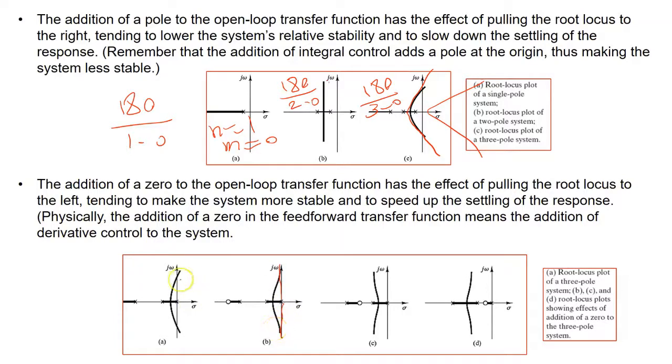Not only that, if you see here, my root locus enters the right-hand side. Here it doesn't. It only stays on the left-hand side. Then when I move this zero closer to the origin, a little closer like here, what happens? The angle is still 90 degrees, but the root locus shape changes, and instead of the dominant poles being very close to the imaginary axis, now they are getting further away, which is a good thing, right?